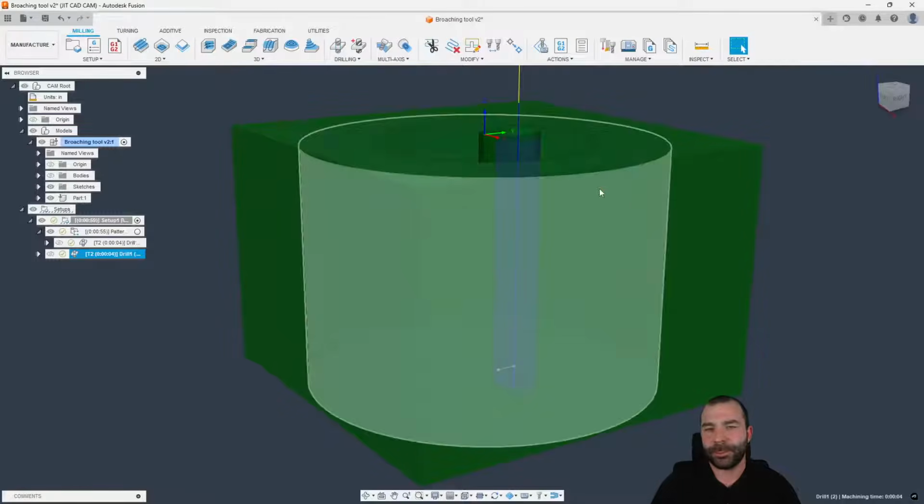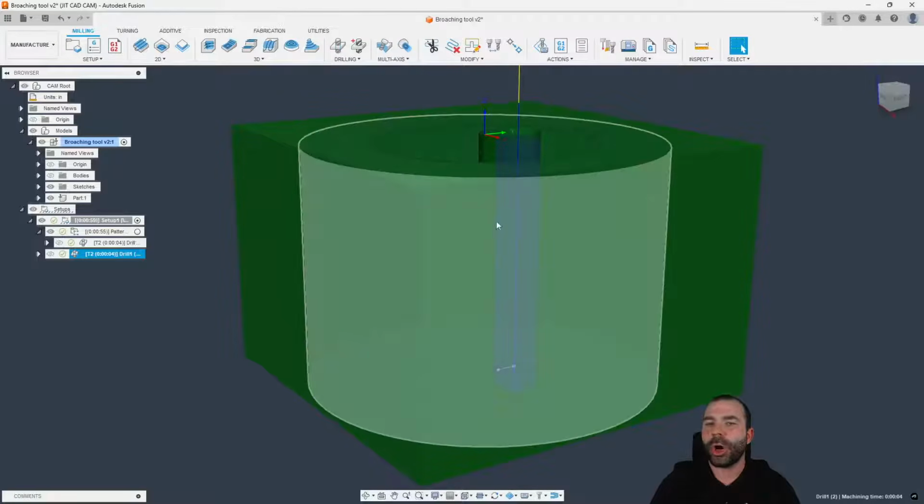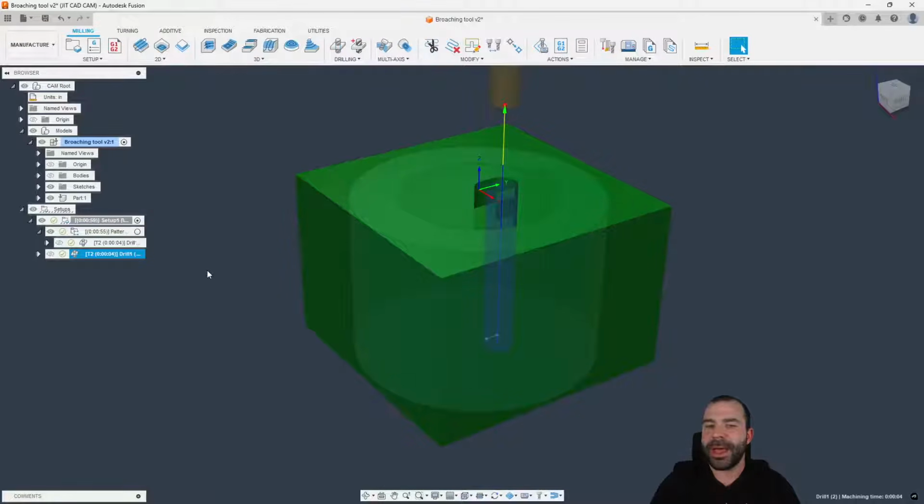So what you guys are noticing here is because I jumped through my setup, we are traveling directly out on my Y-axis and creating that pattern of broaching outwards in the Y direction, or the 12 o'clock position in this part. Now, for some of you, you're not broaching all the time. We don't need to get super crazy with this.